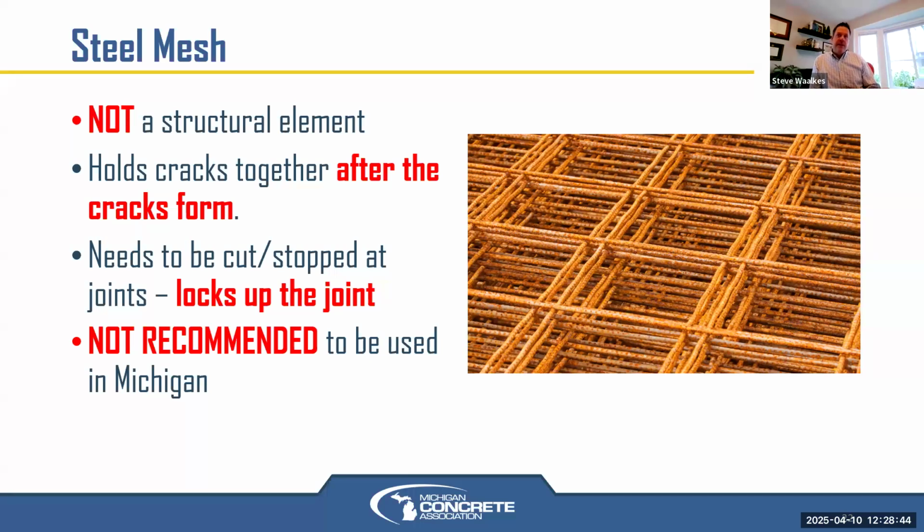Yep, very good question. Every type of facility will probably have different specs. So yes, airports, if it's a commercial airport, it'll be FAA. If you decide to do some work at a general aviation airport with aircraft traffic under 60,000 pound gross aircraft weights, you're allowed to use highway specs. So then you can use FAA, but you could use MDOT specs then. Again, MDOT would govern any federal aid stuff, even built at the city or county level, typically, unless they choose to use some special provisions or other which are approved. But then at the city and county level, non-federal funds, they can use their own specs.